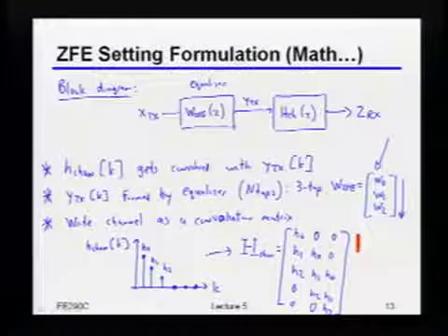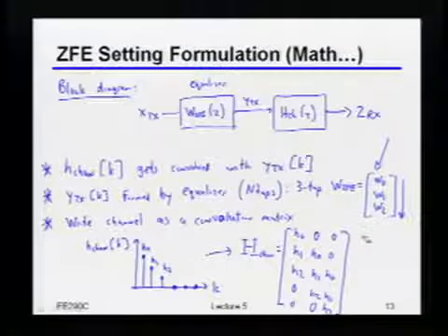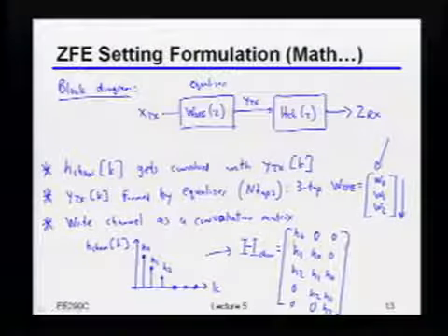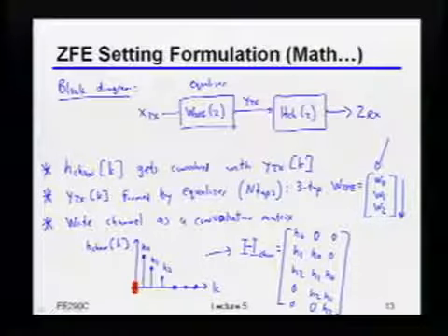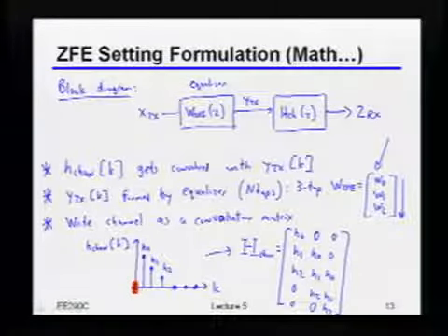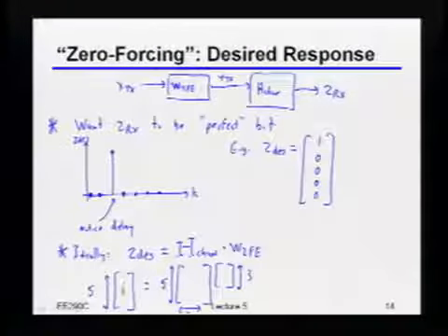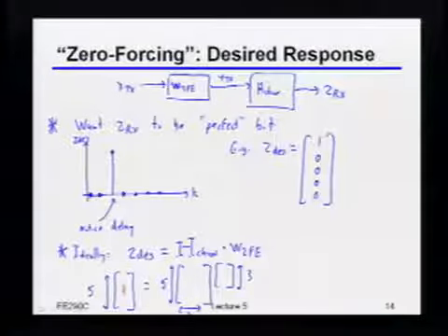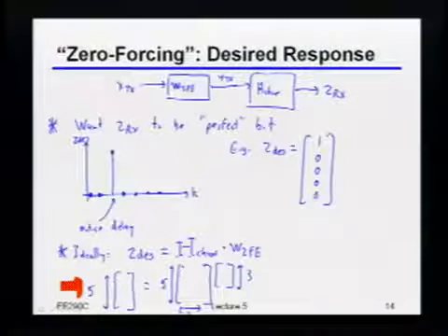Okay. I guess, right, for equalizing on the transmitter, time is relative to the transmitter. Okay, well, so that's right. So you have to be careful about, in this thing, if I put a 0 right here, you still would have needed to shift your z desired, right? Because the z desired is coming out on this side. So if the channel itself had delay in it, then you'd have one symbol of delay in that z desired over here just from the channel. Does that make sense?